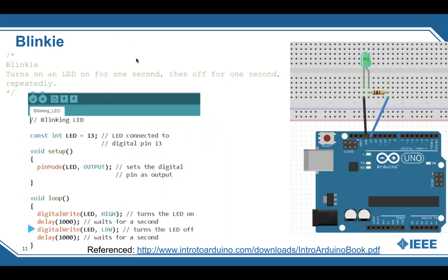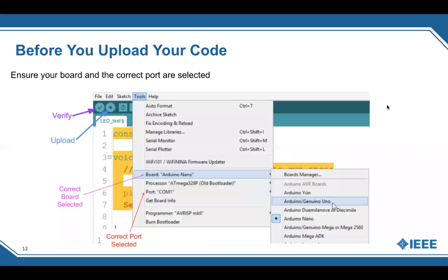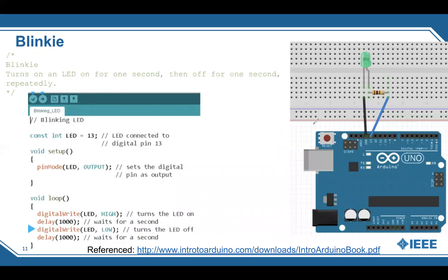And now that we've done that, I'm going to show you how it's connected to the breadboard. So for the breadboard connection, we have it connected to pin 13 down here. And pin 13, like in our code, we said was connected to the LED. You see it's connected to a resistor here, and you're probably wondering why the resistor. You'll learn later on in 201 or 211 that you need some resistance in order to ensure that the current's not infinite.